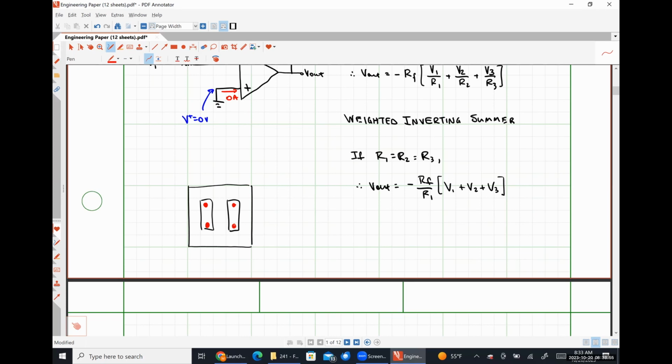And that's why it's one of the most useful things in piezo-resistive sensing. So I think you might still be able to use a nickel strain gauge, but it probably won't be as rigid as what you would use in a bathroom scale, or definitely not at a weigh station measuring the load in the back of a truck, because you don't want it to completely, yeah. So the resistance is based on the shape of the metal? Right. When it's mechanically deformed, the resistance changes. Yep, that is piezo resistivity in a nutshell.